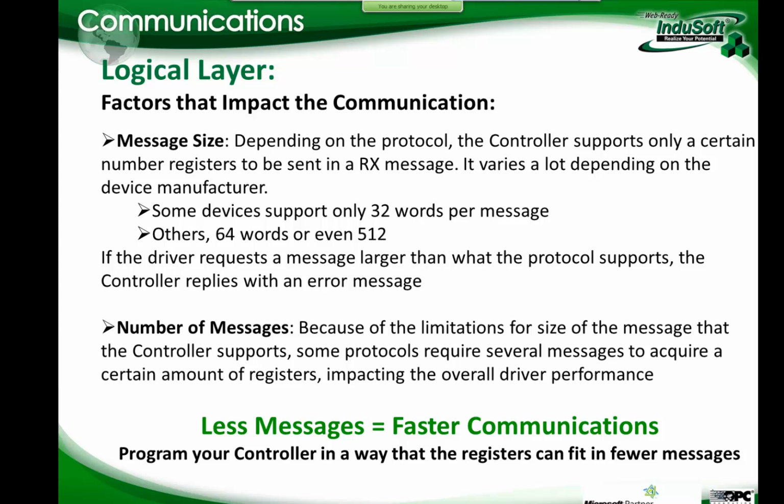So, some factors may have a big impact on the communication at the logical layer. First is the message size. Some of the more modern protocols support more bytes per message, but in the past it wasn't like that. Some of the protocols that have been out there for a while have a limit on how many bytes or words they can exchange. Some of the very old PLCs support only, let's say, 32 words per communication, and some of the current PLCs support around 1,000 bytes per communication.